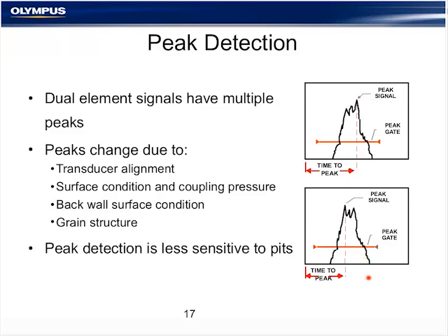So if you chose from the previous slide, as a flaw detector user, not to use flank detection and instead to use peak detection, you can still run into inaccuracies due to these switching peaks from the waveform. So again, especially in pitting, peak detection is also maybe not the ideal solution for thickness gauging, and this can cause some inaccuracies.